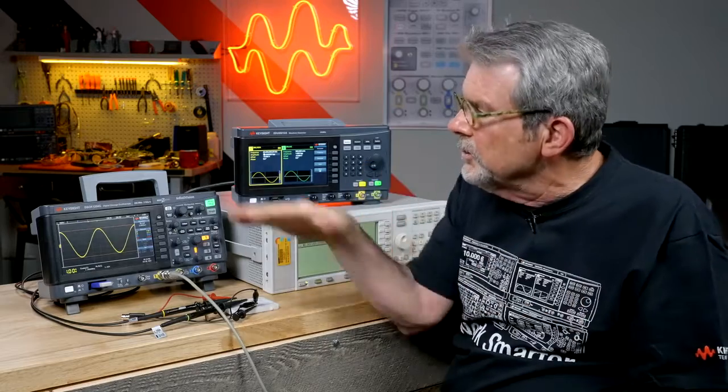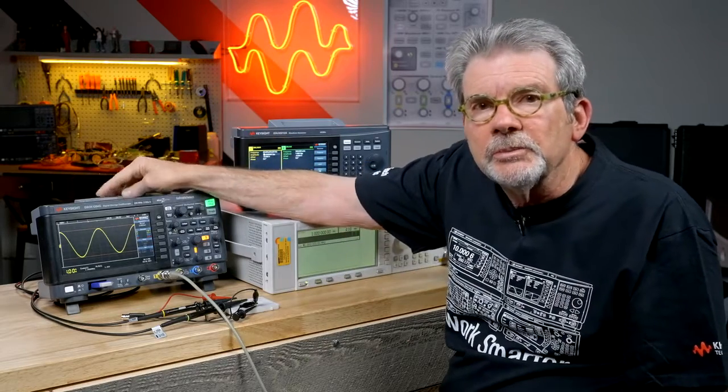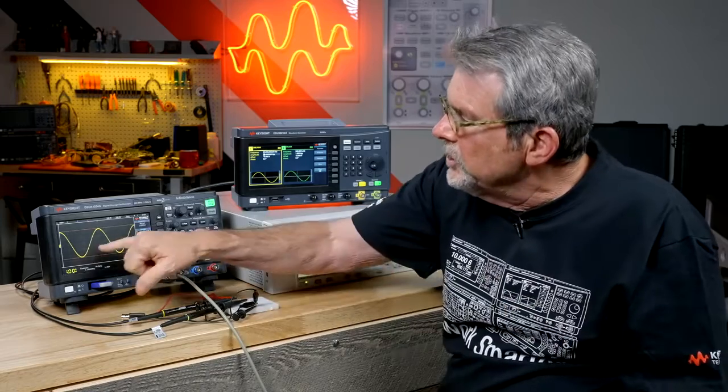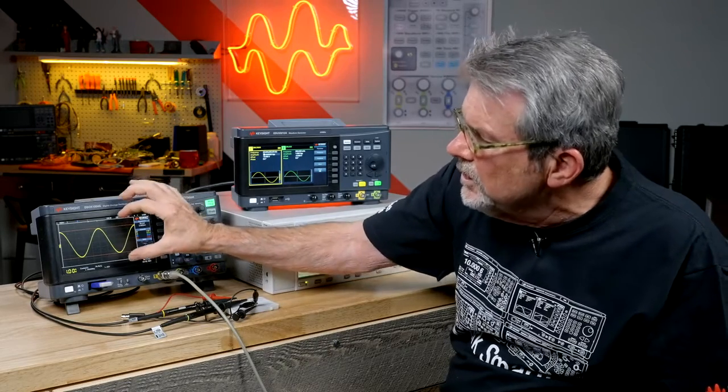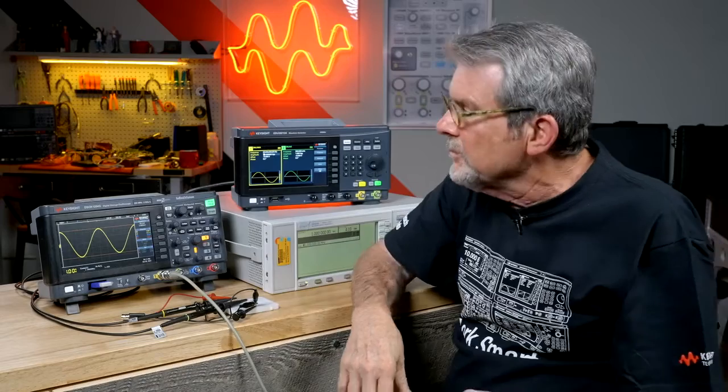application note. Now, there's one more important specification we want to demo, and that's vertical resolution. Scopes use ADCs, or analog to digital converters, to convert an analog input into discrete levels. Most entry-level scopes like this one have 8-bit A to D converters. And so 8 bits means 2 to the power of 8. They resolve into 256 discrete levels over approximately 10 divisions, which is approximately the screen height here.